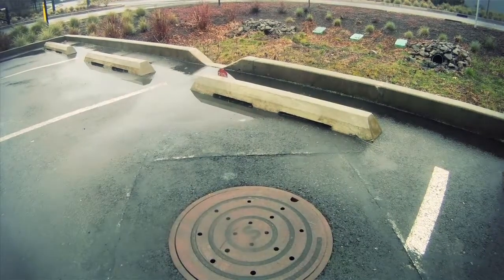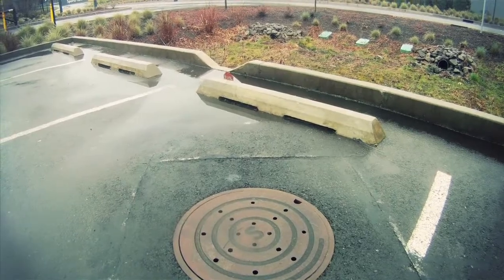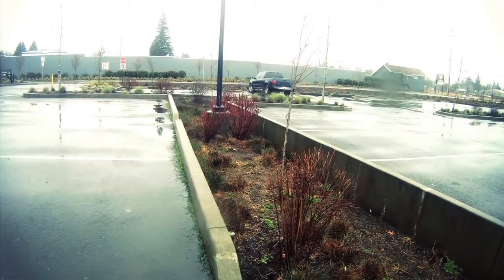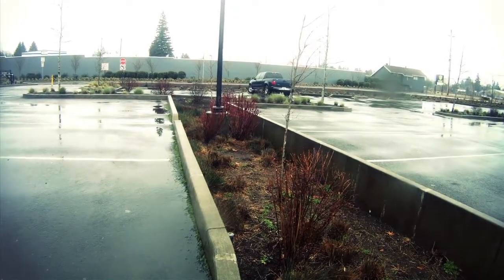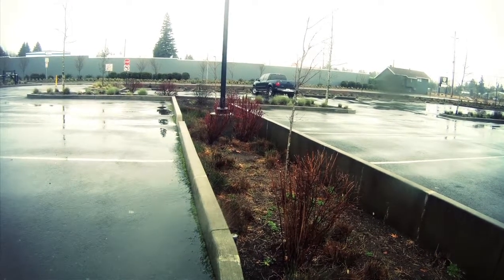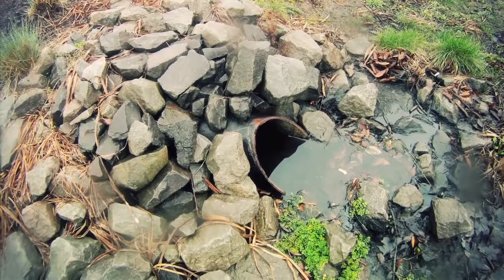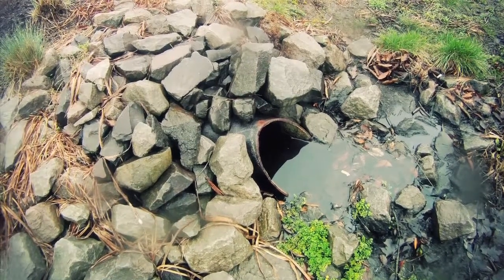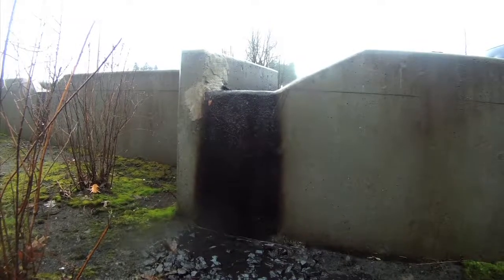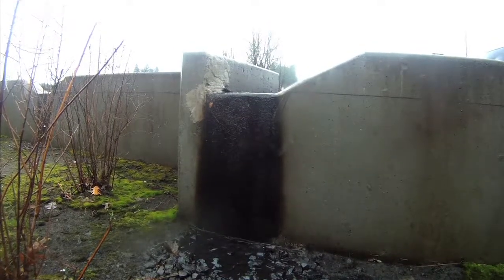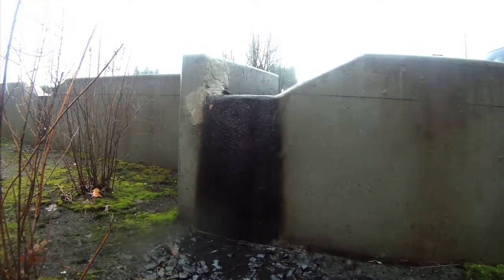For example, bioretention is an ideal rainwater management strategy for median strips, parking lot islands, and swales. These areas can be designed or modified so that runoff is either diverted directly into the bioretention area or is conveyed into the bioretention area by a curb and gutter collection system.